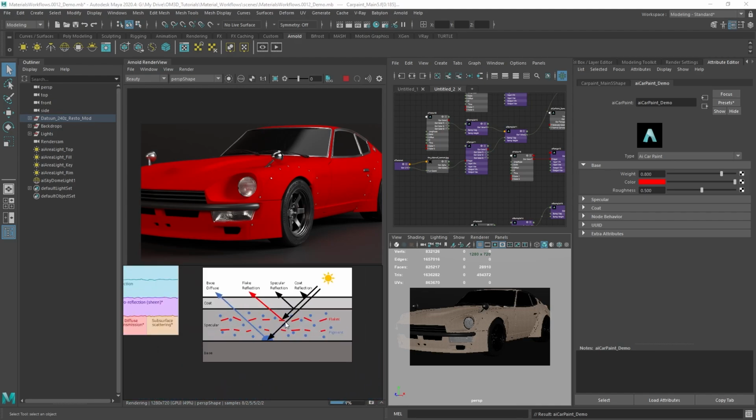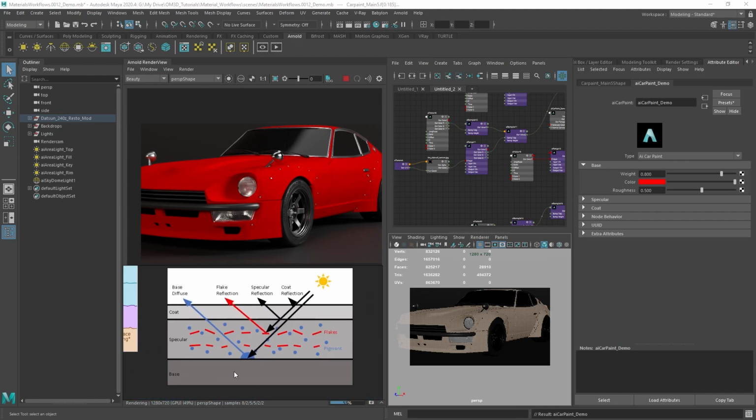All right. Now I have a couple of references here. As you can imagine, there's a base coat, a specular coat, and then there is the clear coat layer. And then you have how the light is going to interact with all of these layers. All of these layers with the coat and the specular are going to be transparent, right? So it's going to pass through the clear coat, hence the name. And then once it reaches the base coat, this is where, depending on how rough the surface is, it'll be how rough the specular highlight is.